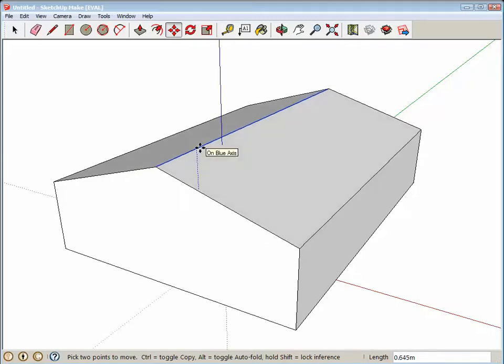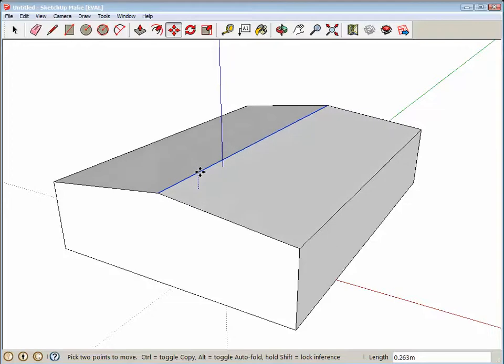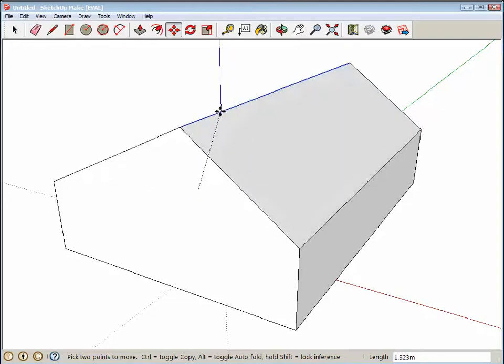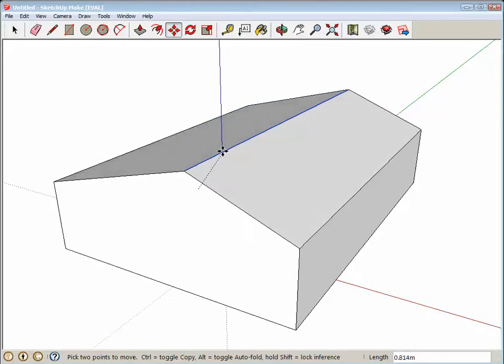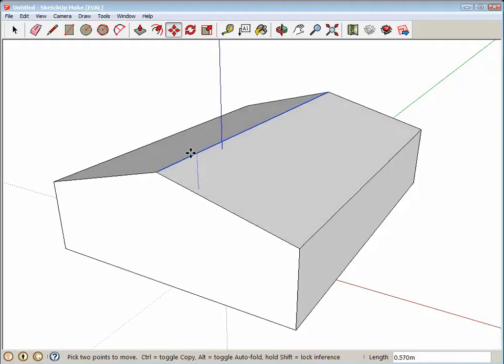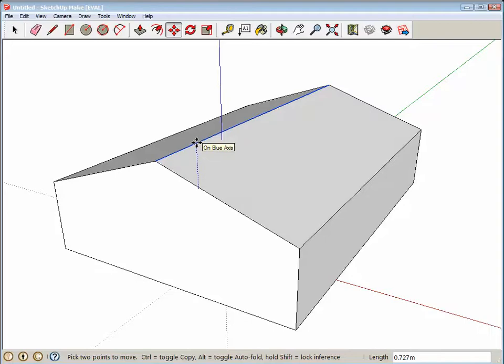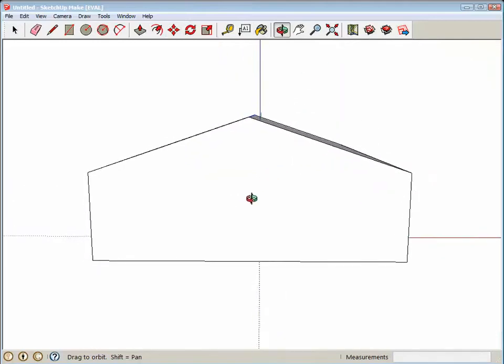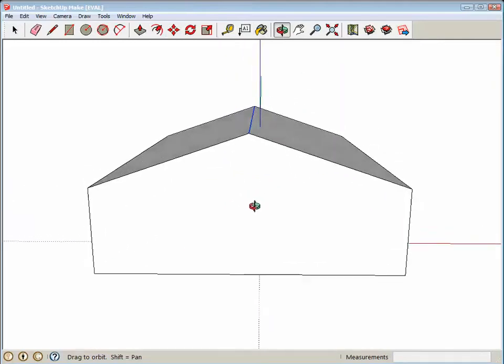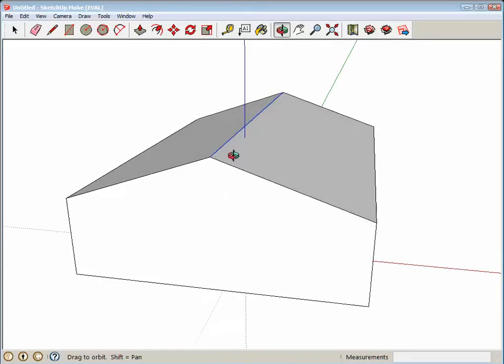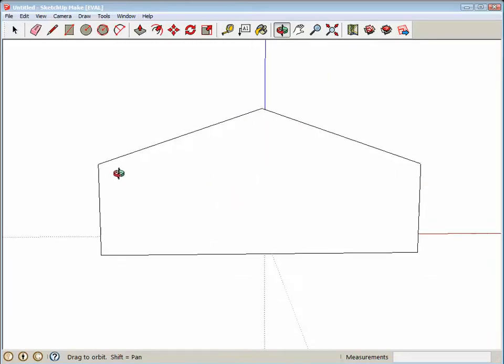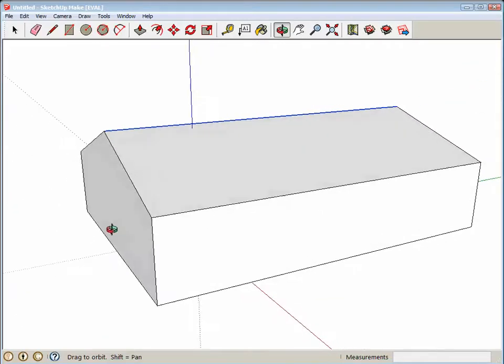Now, you'll see that the dotted line vertical here is blue. That means I went along that axis. Now it's gray or black when I go this way or that way. It will snap into position right there once I'm having lifted the line straight up and down like that. You can take a better look at it like this, and you see that I did hit the midpoint right, and it is symmetric. Although the building's not centered on the axis, I do have equal angles and equal lengths here for the house. Alright, so that's the basic structure of the house.